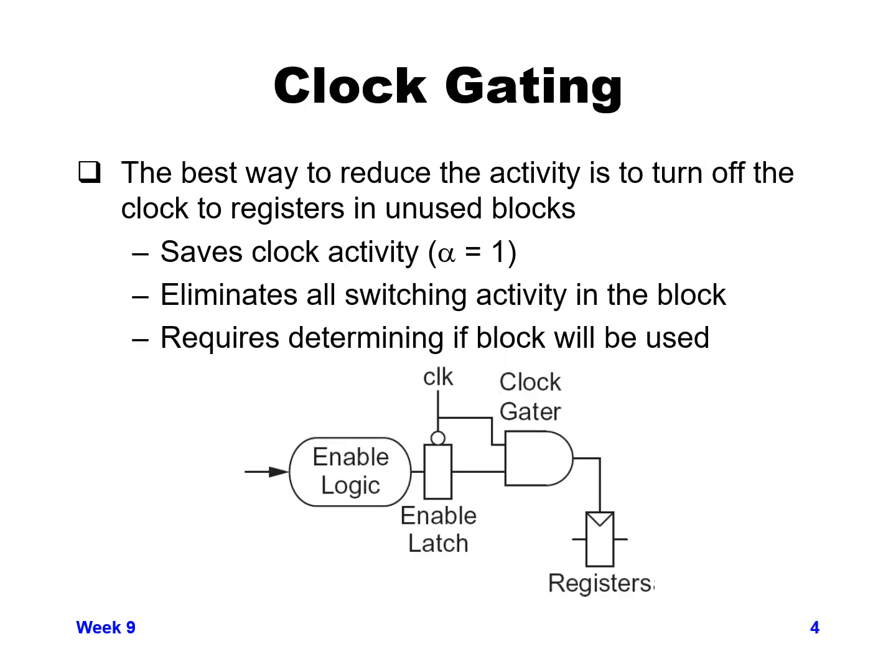As I already mentioned, one way to reduce power is to try and reduce the activity factor of your average logic. And on the last foil, I showed how activity factor does depend on AND and OR functions: you will get lower activity factors in some cases going through the logical ANDing and ORing of different data signals.